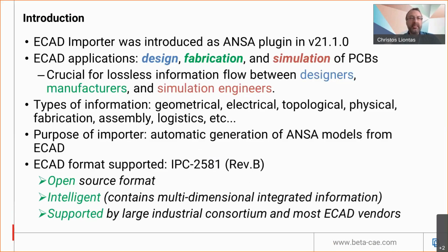So ECAD can contain many types of information like geometrical, electrical, topological, physical, etc. And the purpose of the importer is to gather all these types of information and integrate it in an ANSA database so that we can generate an ANSA model from the ECAD that reflects all these properties of the model.